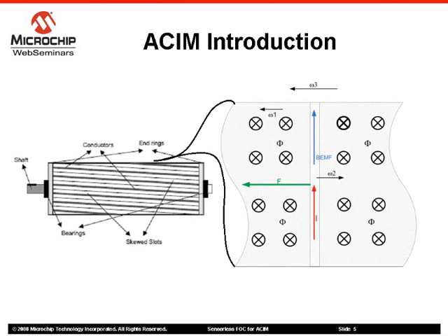The rotating stator flux induces the back EMF in the rotor squirrel cage, which generates the rotor flux. The motor starts spinning as the rotor flux is trying to catch the rotating stator flux. The rotor will never be synchronous with the stator rotating currents because if they were to be synchronous, no back EMF will be induced in the rotor cage and no rotor flux is generated.